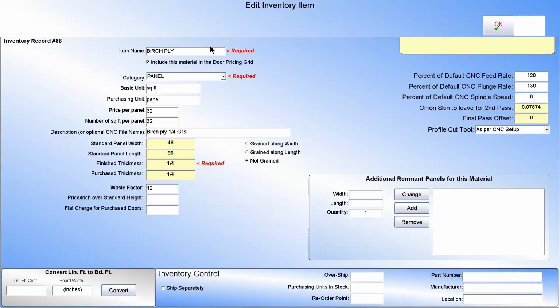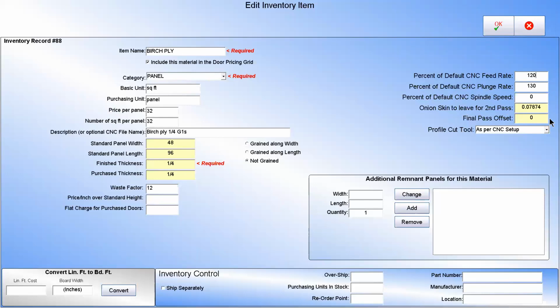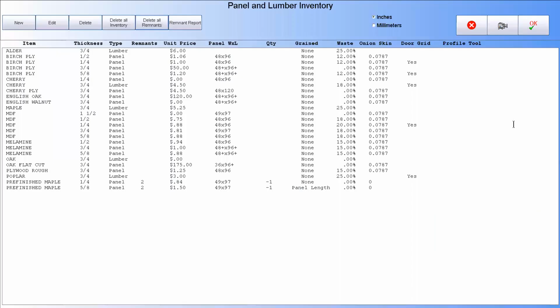The point is that for each material, your speeds, your plunge rates, your spindle speed, your feed rates can all change according to what's appropriate for that particular material, without you having to worry about it. And so you'll put one material on there and run it, and automatically your router is going slower in different areas, or it's going faster in different areas.